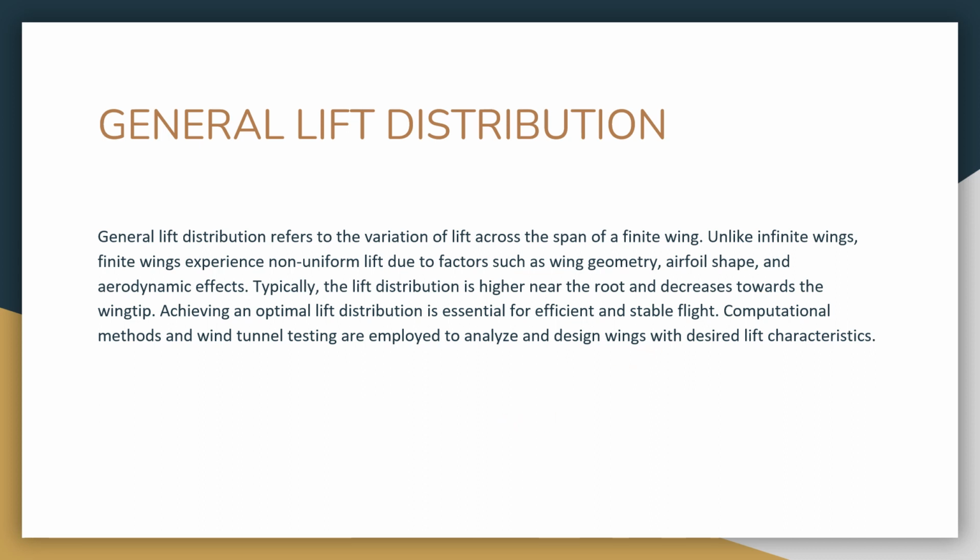So apart from that, the general lift distribution refers to the variation of the lift across the span of a finite wing. Unlike an ideal wing, finite wings experience non-uniform lift due to factors such as wing geometry, airfoil shape, and aerodynamic effects. Typically the lift distribution is higher near the root and decreases towards the wingtip.